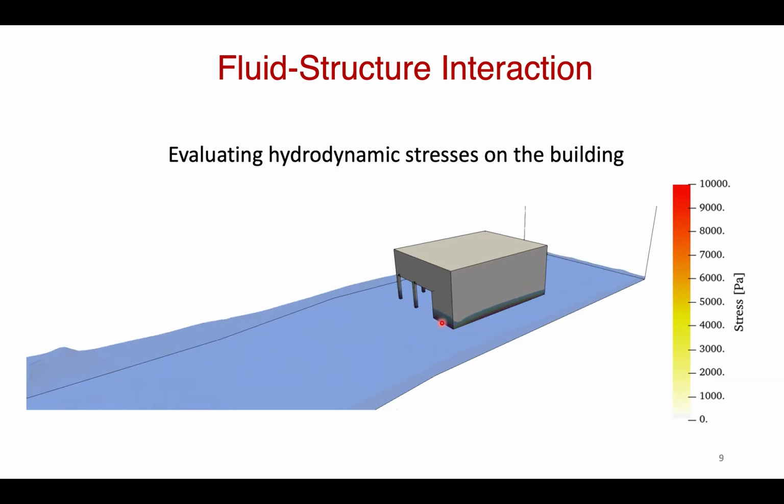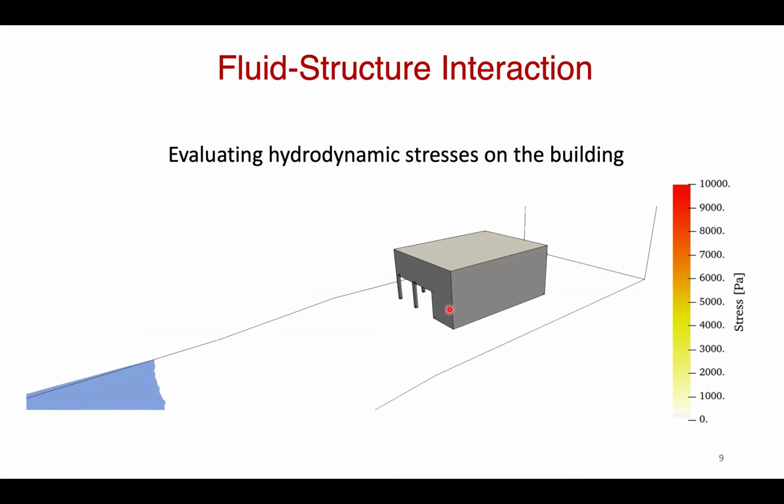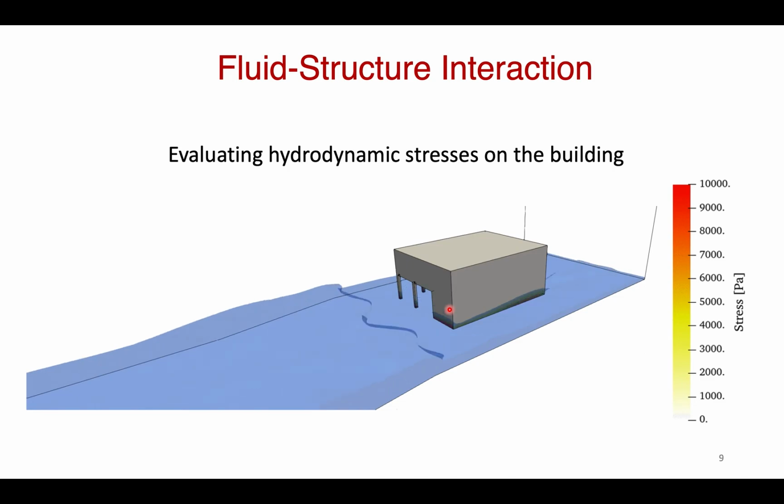As shown here, this shows the stresses, and you see stresses are larger, but they also depend on the turbulence. Sometimes you see these surges come, and then a big momentum bulge suddenly strikes the building, and so we have these large loads, not only here but sometimes even higher, because some momentum bulges can be completely chaotic and turbulent. So it is very important to account for this turbulence in these kinds of studies, and large eddy simulation shows that we can use that technique to deal with these problems.